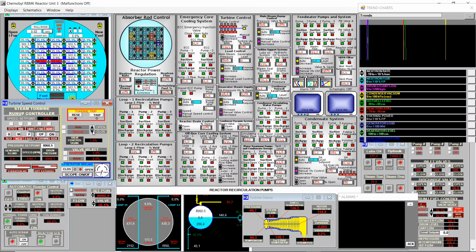I will close a bit more the startup valve. And now we see how at this opening the rotor temperature starts increasing, because it's not cooled down enough by the steam temperature. You see that now the steam is cooler than the rotor, so the steam is cooling down, not heating up. I need to reopen a bit. Let's reopen at 1.9, and you see that the rotor is decreasing temperature again. So I will keep this valve at 1.9.